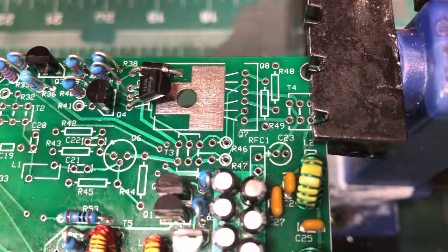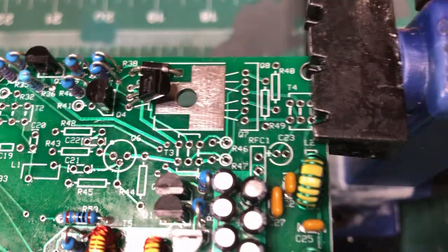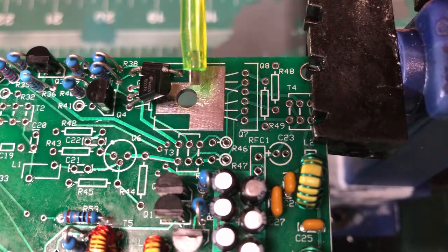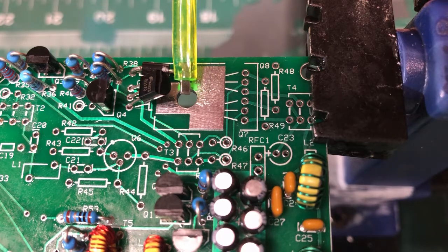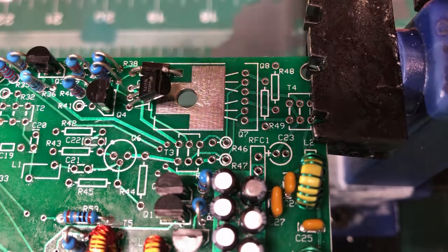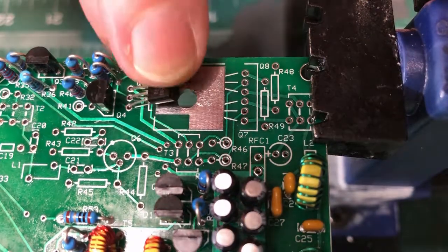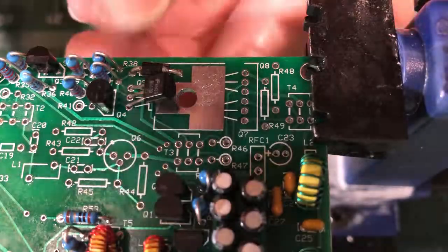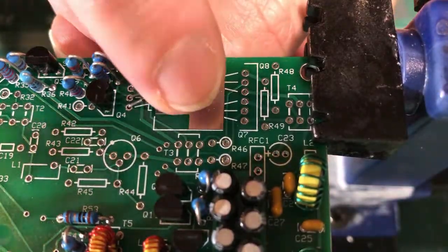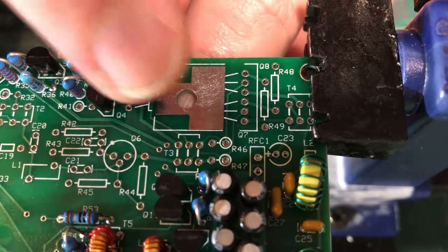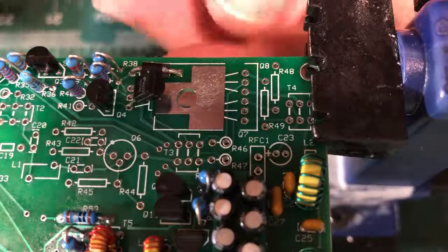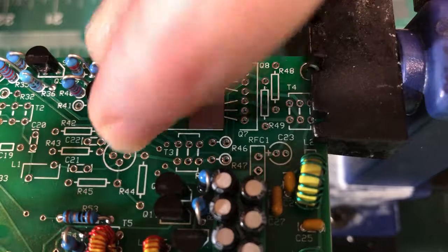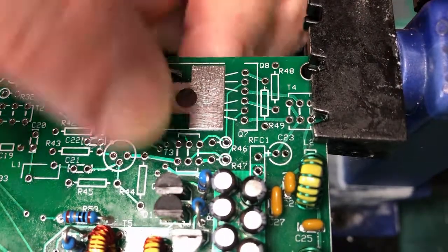So just to explain this, the two final FETs go here and here, again bent backwards, and there's a nut that goes through here, and then there's a heatsink on top. So when you're installing these, you need to make sure there's enough clearance right here for the nut to go through. So I need to push that down a little bit more, I think, before soldering it in place. It's a fine line, because if you don't put it far enough back, I'm probably going to have to bend those at a greater angle there. So let me just do that.